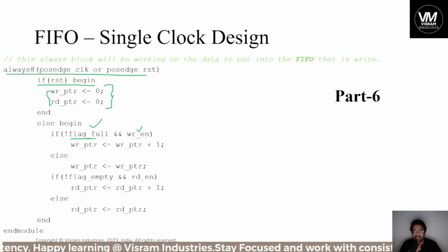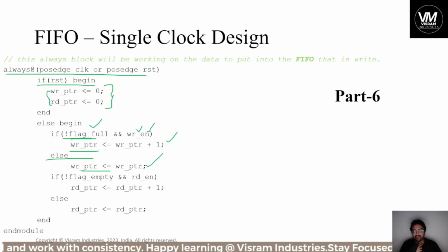So if not flag full, meaning you can write something, and write enable is 1, the write pointer is incremented. Else the write pointer is the same.